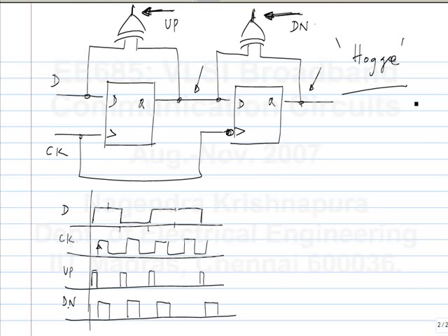The second thing is, if you are really oversampling by a lot, let's say you are transmitting at 100 megahertz, but you are sampling at 1 gigahertz, you actually in that case don't need a clock and data recovery circuit in the analog domain. You can get the samples. It's okay if they are misaligned a little bit. From the recovered samples, you can anyway reconstruct the data. So the clock and data recovery circuit can be done digitally or in some other way. Sometimes you do that. You do what is known as blind oversampling. You just take a lot of samples, and after that you digitally see where the data is going.